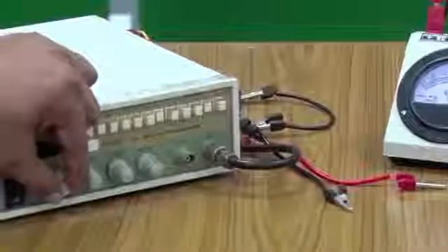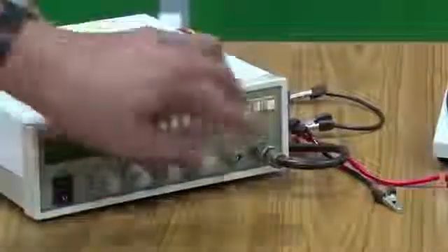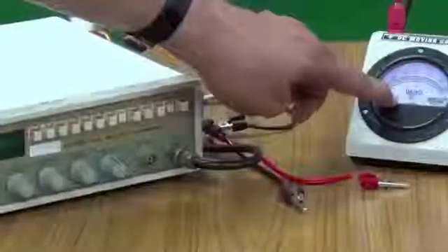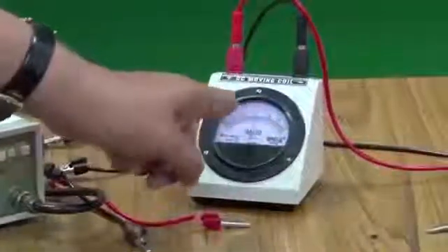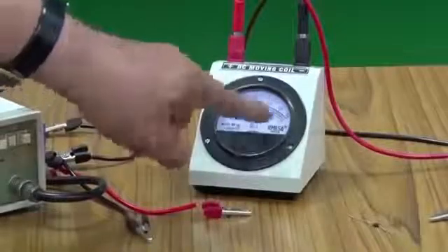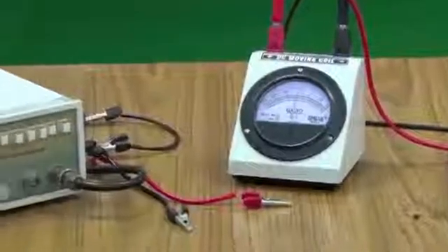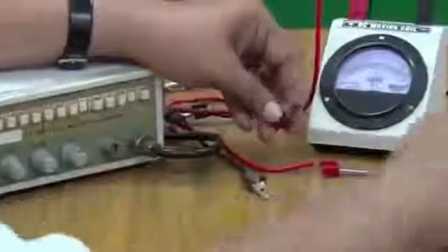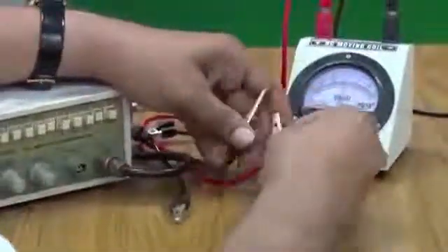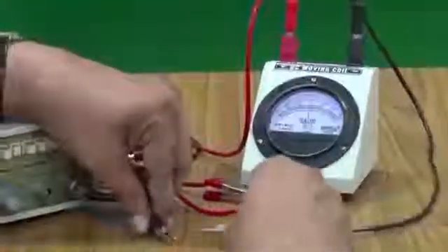So what I will do is I will take a very low frequency signal from here, and I will put this directly into the galvanometer, so that AC voltage will go into the galvanometer and the needle should deflect on both sides, showing that it is changing direction, the current is changing direction. So first let me do that much of it. So let me put it on, and then I connect the two ends of the galvanometer to these 2 points where I am getting my AC voltage. This is connected and this is connected.